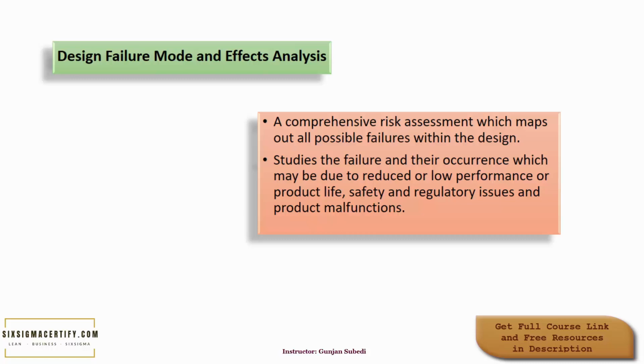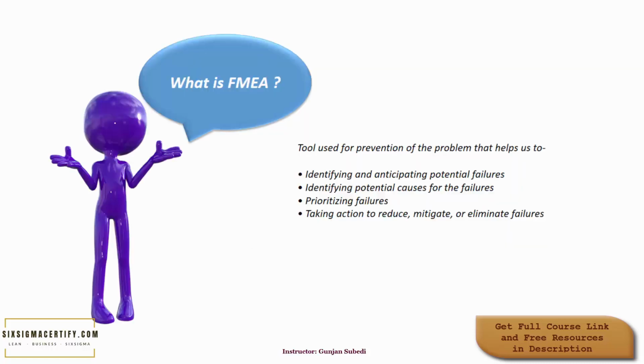It is a comprehensive risk assessment which maps out all possible failures within the design. The failure may be due to reduced or low performance of the product, low product life, safety and regulatory issues, and product malfunctions. DFMEA studies these failure modes and their probability of occurrence.